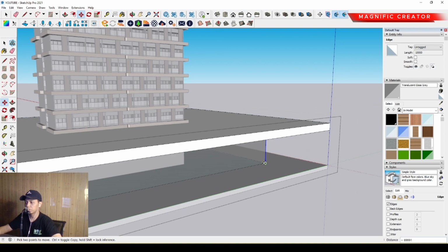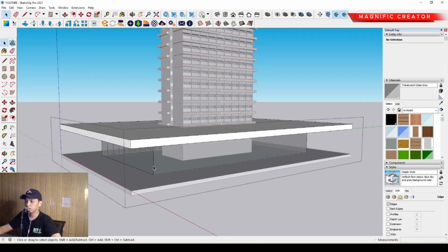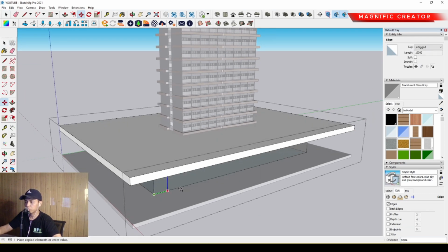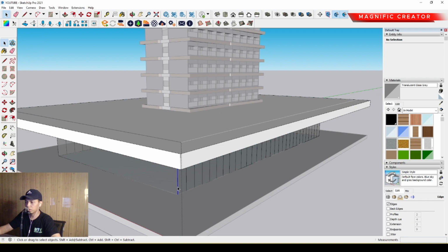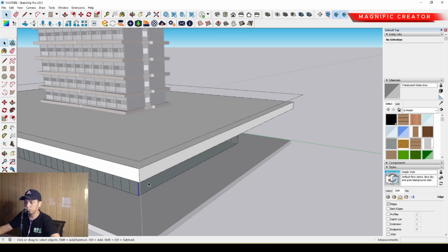And we can place it, and we can type 30 slash, okay, something like this. We can move, control, position on it, and type 30 slash enter. We can place it, move it, we can type 15 slash.